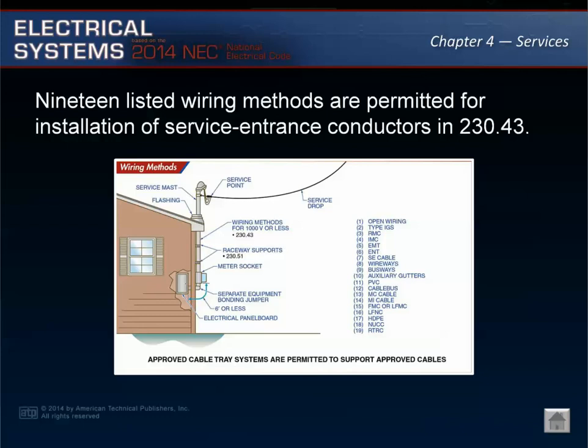No matter what wiring method is selected, the service entrance conductors shall be installed per the specific NEC requirements for that particular wiring method. For example, if a type MC cable is selected as the wiring method, the service entrance conductors shall be installed according to all the provisions of Article 330, metal-clad cable.